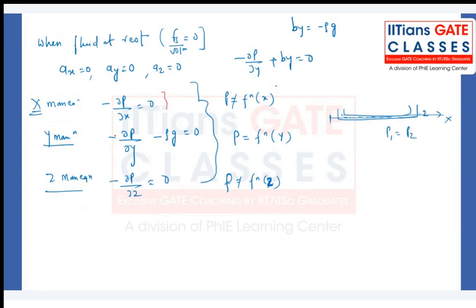For fluids which are continuous at the same horizontal level, we directly equate the pressure. One limb is connected to the tank whose pressure we want to measure, the other limb to the open side, and we place a certain liquid called the manometer fluid. Whatever height is raised gives me the pressure value directly, because at this point we are just equating the pressure.